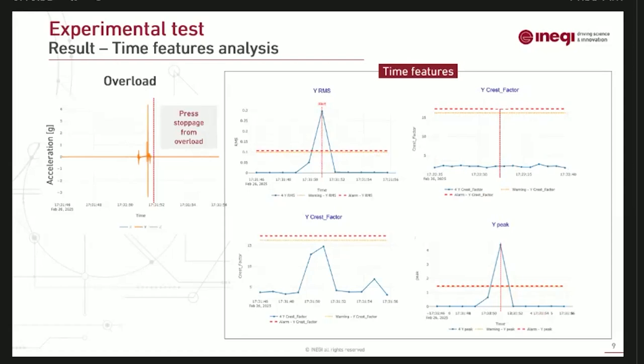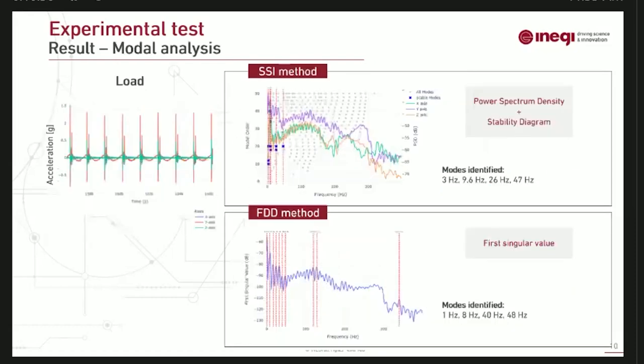Then for the modal analysis on the loading condition. Here, in the SSI method, I'm presenting the power spectral density. So we have the signal decomposed by its frequency components in the three axes. As you can see, it's very noisy. I applied filters, but it needs more filtering.